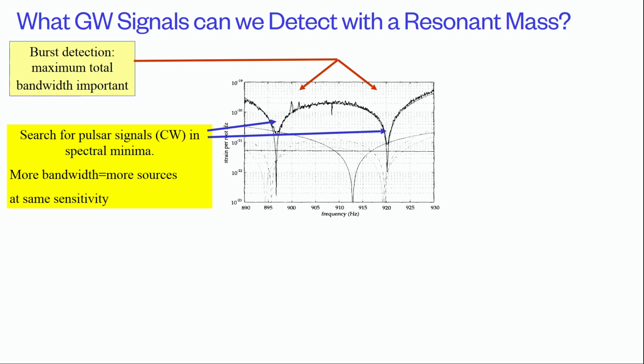And that's what a template is. So if you know what it is, you can work out the template from knowing the frequency spectrum of your noise and what the signal looks like. For LIGO, which is pretty broadband, we don't have to worry much about what the noise is doing. But if I'm doing it for a bar or something that's narrowband, you have to worry about that transfer function and put that in your filter.